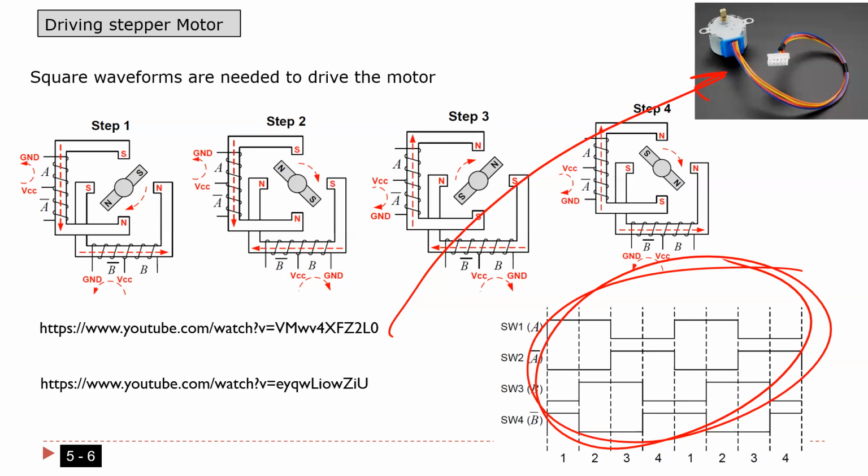So output compare is going to help me to do that. Okay, output compare can help me to do that, because this is the most critical thing. I'm going to say it again because this is the most important thing. Okay, guys. In chapter 3, we generated a square wave. So why do you want to generate a square wave again now? Big difference. In chapter 3, we took too much time from the CPU, from the microcontroller. But here, most of the work is going to be done by the external circuit. I'm gonna take very little time from the CPU. This is the main difference. You get what I'm saying?